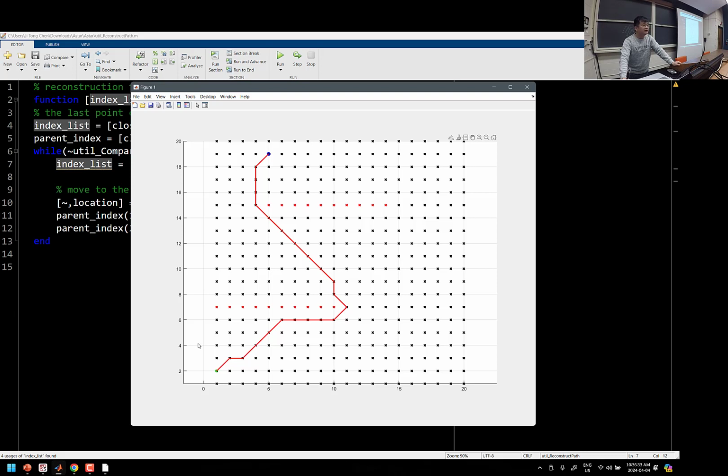If you do the tunnel, I think you have a gate traversing task, right? If I have a gate traversing task, then you need to design a tunnel on the map based on the discretized map. So you basically just allow one tiny tunnel from the starting point to the end point, and you run the A star algorithm.